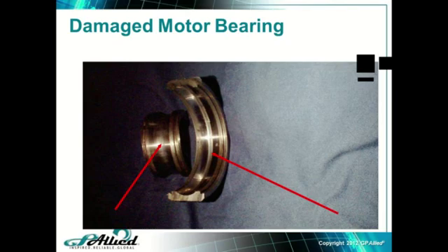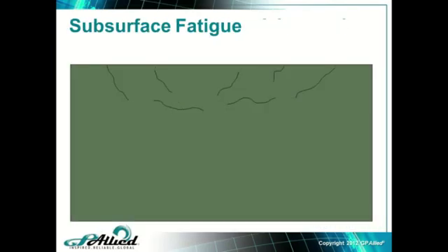And if you go to Radio Shack and get one of the little $10 microscopes that takes a AA battery, you can set it right on the race and focus it, and you can actually see these subsurface cracks. Now, the good thing about steel, and most things in general, is that if you're only talking 5, 6, 7 microns deep, it's transparent. You can actually see the cracks, but you can't feel them. And that's why we can see that discolored track on the race. Now, if I allow that to keep going, eventually all those cracks will connect.